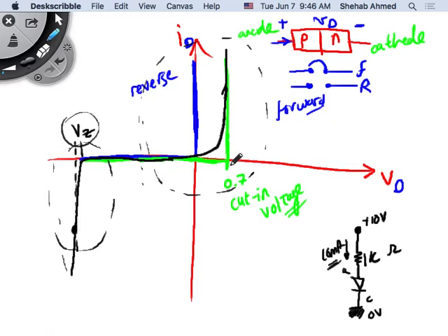You will see that if you put an external circuit and you are able to overcome the barrier voltage. Overcoming the barrier voltage means you started conducting, right? When you start conducting, this diode is responding with a minimum of 0.7 volts opposing you. Remember, you have to make the anode at least 0.7 volts higher than the cathode. So this 0.7 volt is like a 0.7 volt DC source opposing current flow, right?